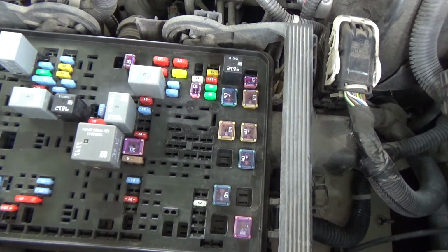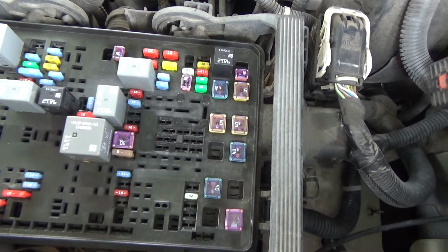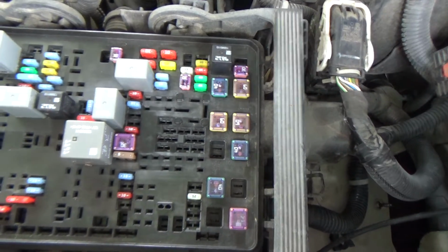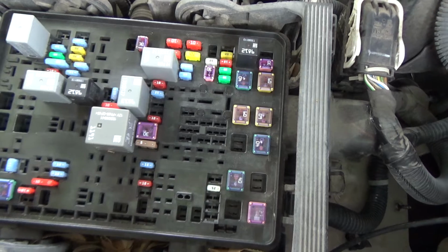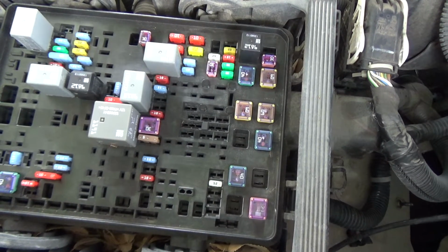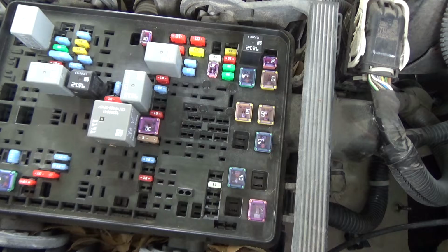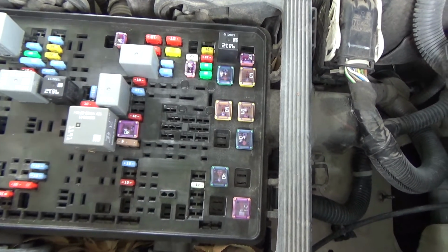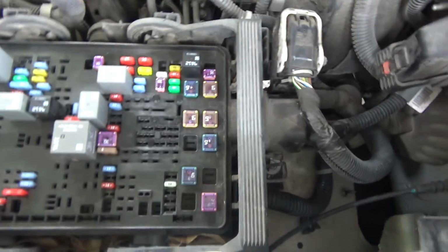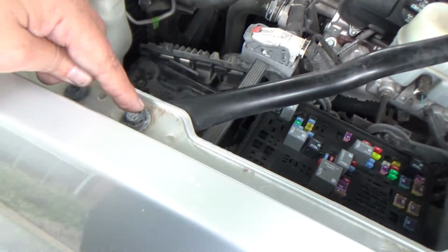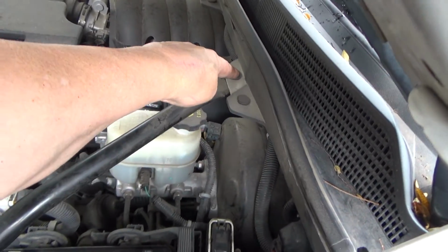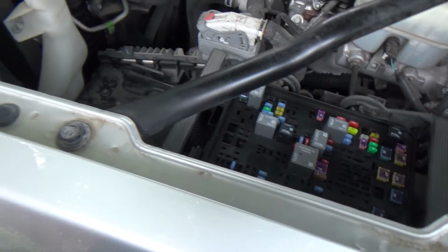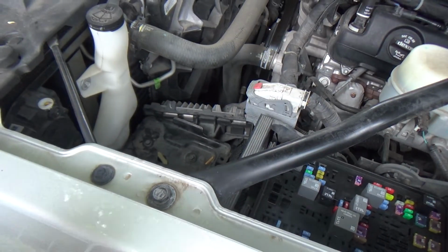So, in my way of thinking, that relay is not changing contacts, changing position. And since the scan tool is showing the BCM is seeing the command, I'm thinking that relay, or possibly a feed going to this fuse box, is not there. So let me get the camera set up. I'm going to go ahead and take this bolt out. I'm going to loosen this bolt, and we're just going to pivot this out of the way. That way we'll have more access to it. So let me get set up here.